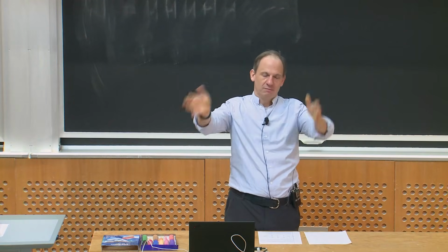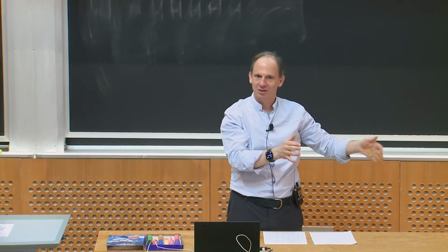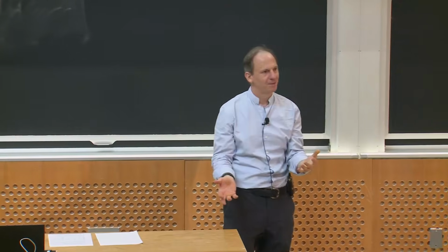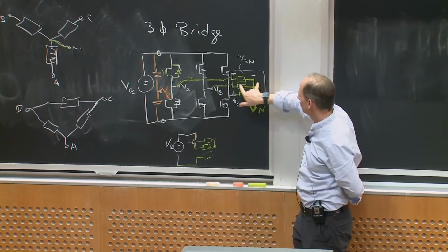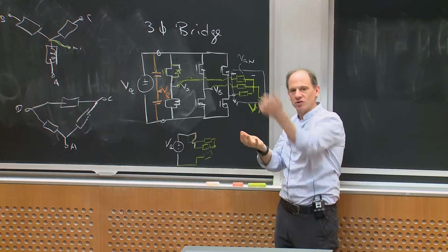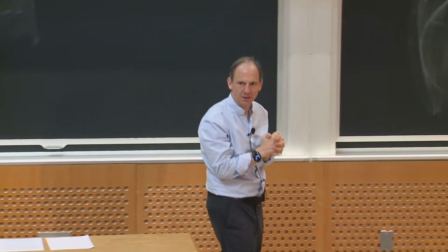The fundamentals are 120 degrees out of phase, but that means that the third harmonics are exactly in phase. So the third harmonics of each of these square waves add at the neutral, and you get a neutral voltage that bops up and down at the third harmonic. Okay? So the neutral contains the third harmonic and actually all the triple N harmonics. All right? And so as a result, just as the line-to-line didn't have any triple N harmonics, neither do any of the line-to-neutral voltages. So if it's a Y-connected machine, the line-to-neutral voltage, which is really what's driving current in this thing, has no triple N harmonics. Okay? Does that make sense to everybody?